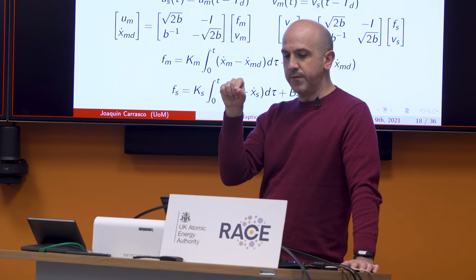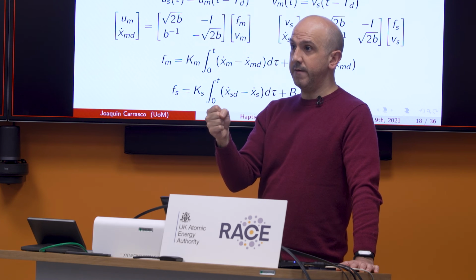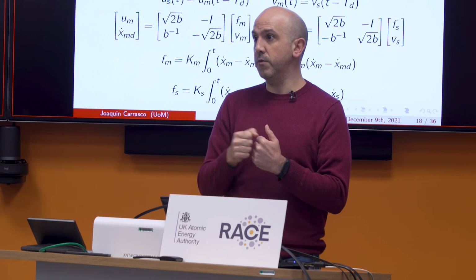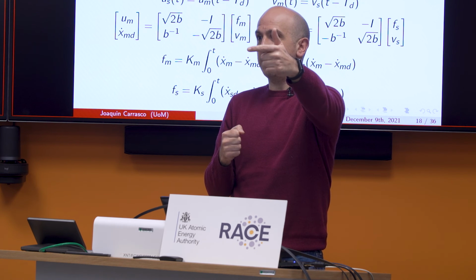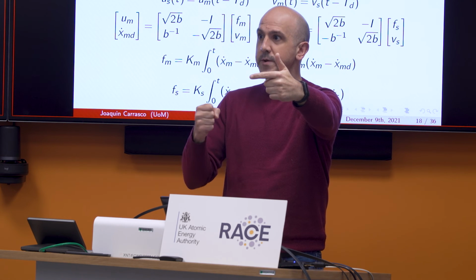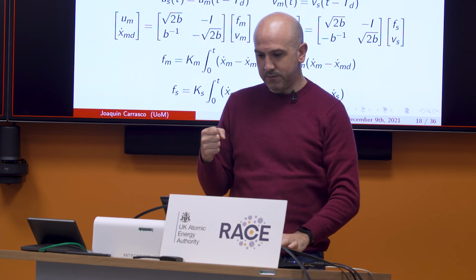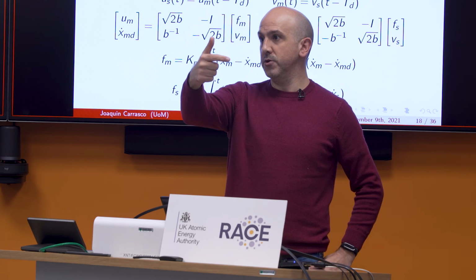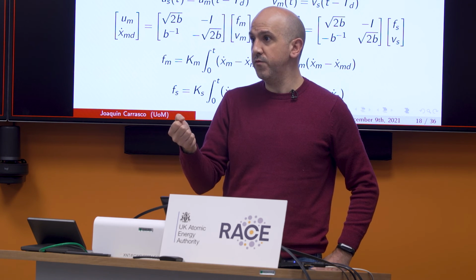But in addition, another problem that you will have there is that evidently when you move your haptic joystick on the local site, the other guy will need to feel a force. And this force is not the force of the environment. It will be the force of the controller moving the robot because you are moving the robot. Do you understand? So actually this force here is kind of significant too, because it's the force that the robot on the other side needs to perform in order to follow the movement of my hand.